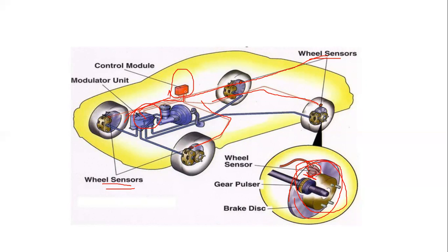This ECU unit will calculate how much braking effort should be distributed to each wheel. This is the major working of this ECU unit. It will calculate how much energy will be distributed to each wheel according to the sensed signal. It's not like ABS. ABS will create a continuous braking and releasing mechanism at an interval of 15 times per second to all the wheels simultaneously.